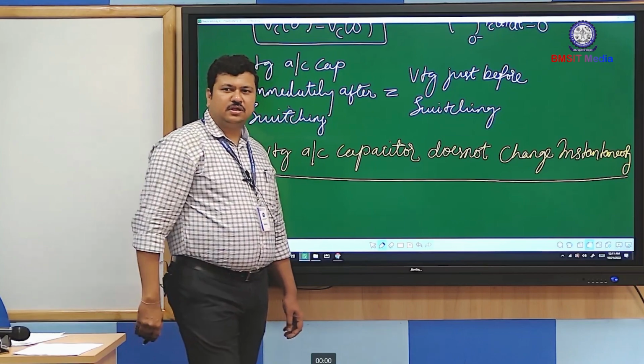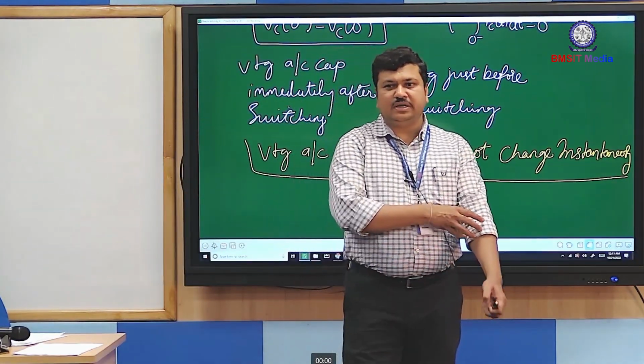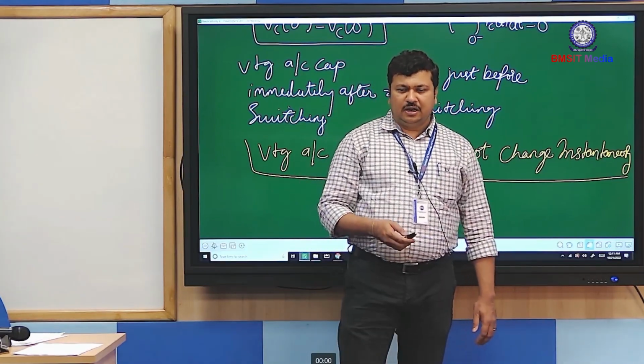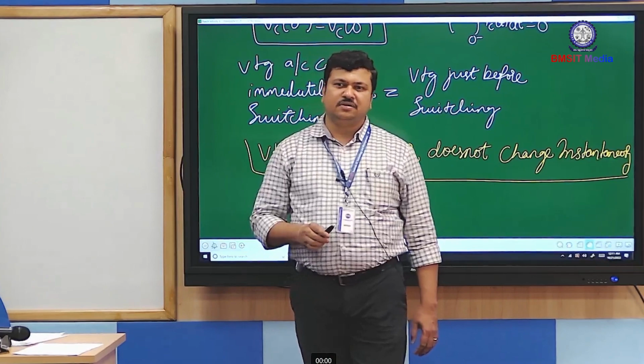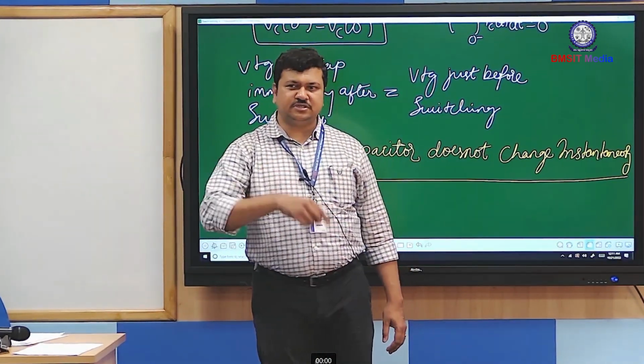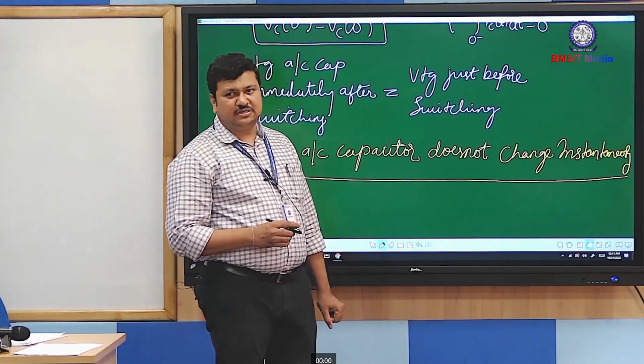Go back now to the single phase AC. There we have talked about the current. We said current lags behind the voltage in an inductor and it leads the voltage in a capacitor. But actually in a capacitor, current is not leading, it is the voltage which is lagging, because voltage will not change instantaneously in the capacitor.